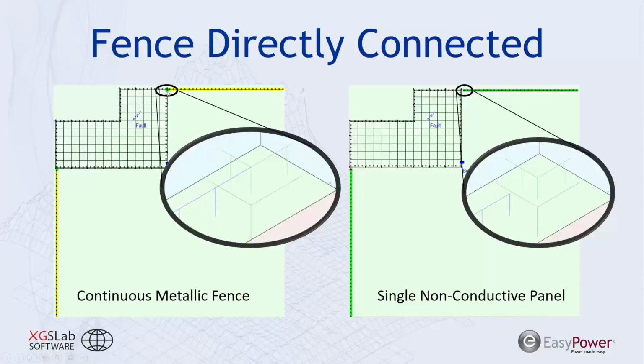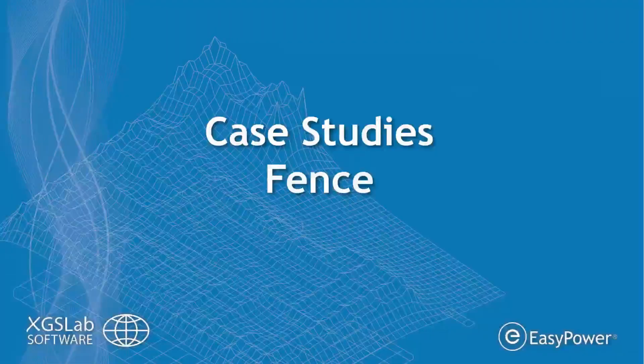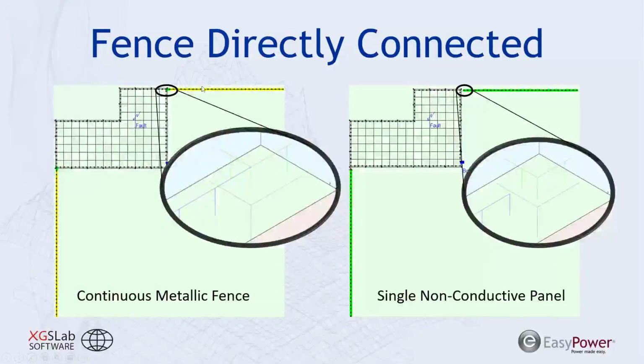And green is indicative of touch voltages that are below the compliance limits for IEEE standard 80. Yellow denotes locations where we are exceeding touch voltage limits for personnel. So we can see during a fault at that station, we have substantial enough voltage that's transferred to this neighbor fence to create a touch voltage hazard.